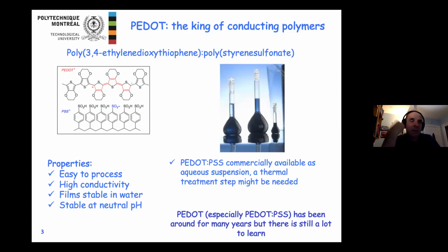Of course you can make your polymer yourself, and there are other advantages to that, but it's now very advantageous to use this formulation because it's available commercially. There are several formulations where you can find optimized conductivity, printability, or optical properties. And the advantage of this polymer is also that it's a water dispersion, which means that we can mix it with other water-soluble materials or polymers to improve the electrical and mechanical properties.